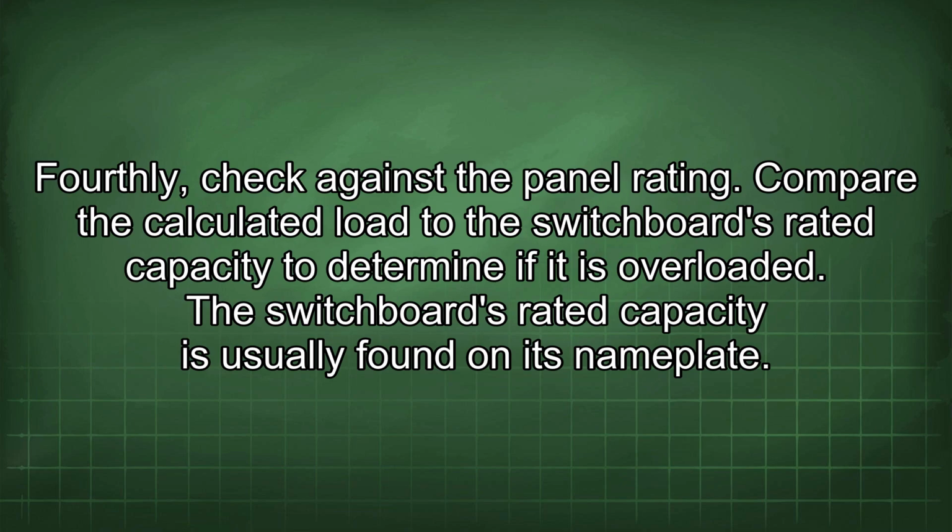Fourthly, check against the panel rating. Compare the calculated load to the switchboard's rated capacity to determine if it is overloaded. The switchboard's rated capacity is usually found on its nameplate.